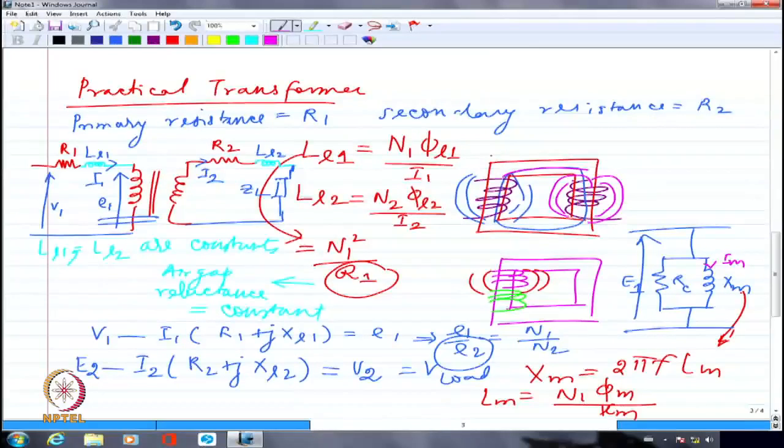Fine? I want you to refer back to the original discussion for a ferromagnetic core having an equivalent circuit of resistance in parallel with an inductance. The resistance is representing the core losses. The inductance is representing the current carried to establish a flux.